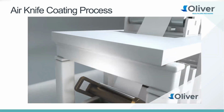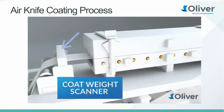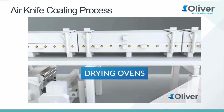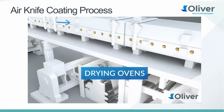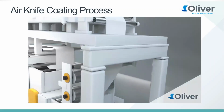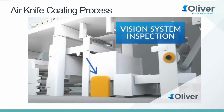And then this is an air knife that's going to be metering off the excess adhesive into a blow-off pan, and then that coated substrate is going to go up through a series of rollers. It's going to have some coat weight check, and then it's going to go into a series of drying ovens to flash off. In this case, it's a water emulsion, so it's going to flash off that water. So you've just got a solid, nice breathable coating on the substrate. And then it's wound off into master rolls.